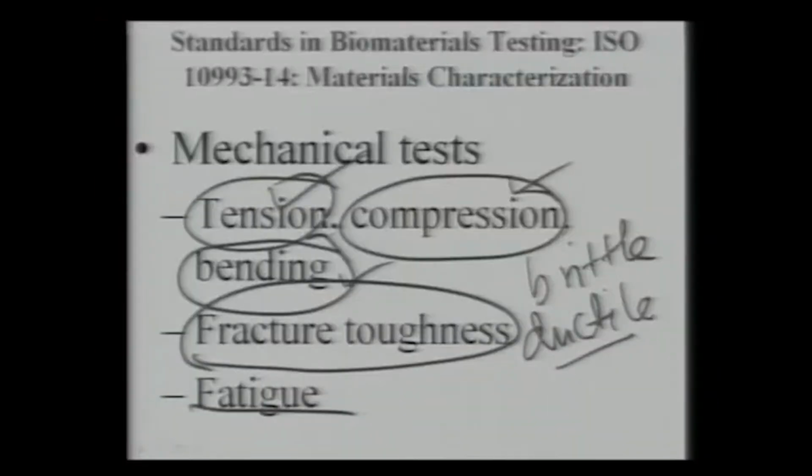Typically, if your material is under uniform stress, then the material will have higher load bearing capability compared to a material under repeated or reverse stress cycles. So fatigue strength is much lower compared to the typical tensile strength of a material. That is a message that you should remember.